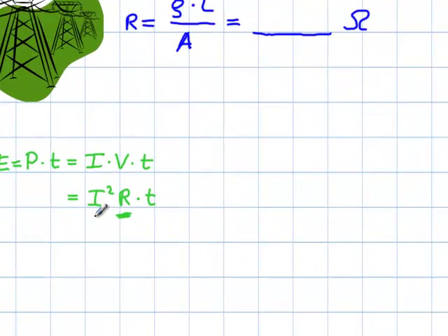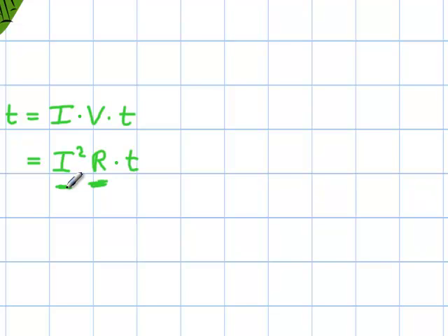And the other one is that the current should be pretty small, and that's why you see such high voltages on the power lines, because after it goes through a transformer from the power plant, the voltage is being stepped up, but the electric current is being stepped down in order to get as little electric current running through the wire as possible with, well, a very high voltage at the same time, so that the power loss within the power lines is relatively small. That's just on top of what the problem asked about, but I figured, hey, this is a problem on power lines, so I might as well mention that.